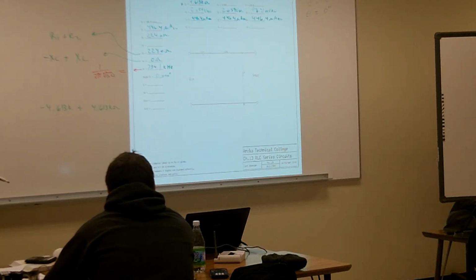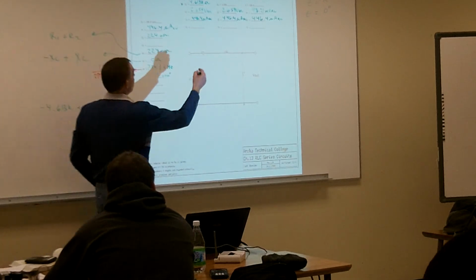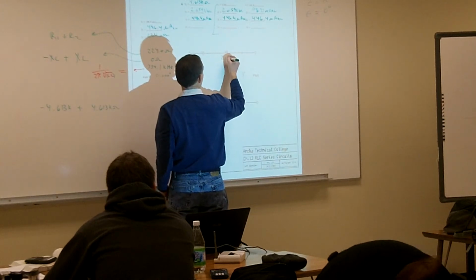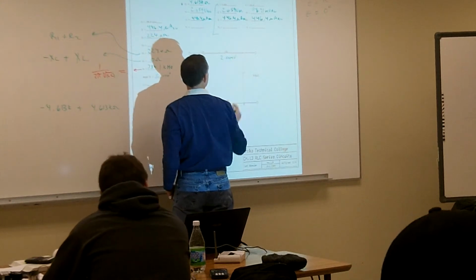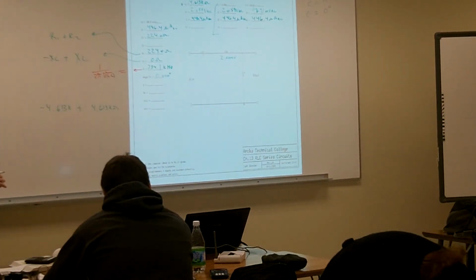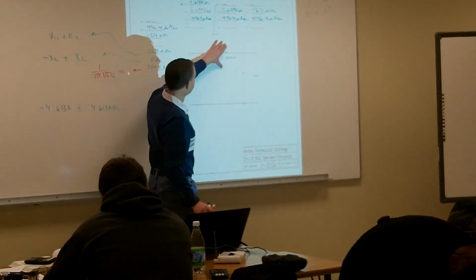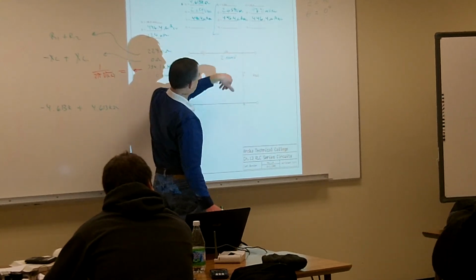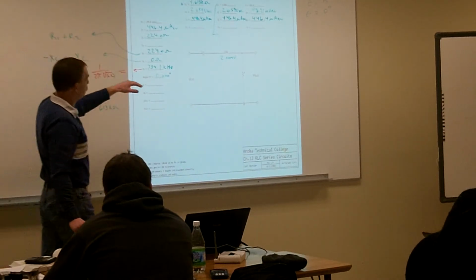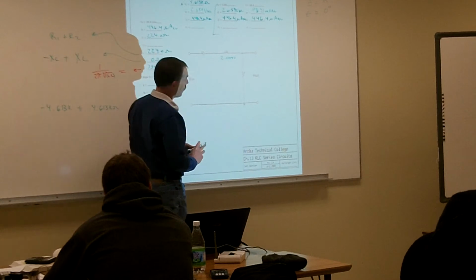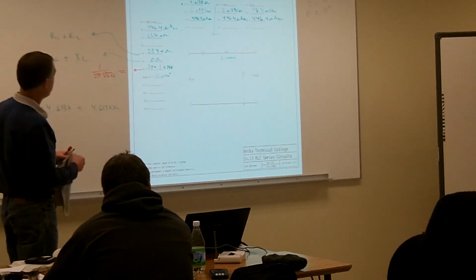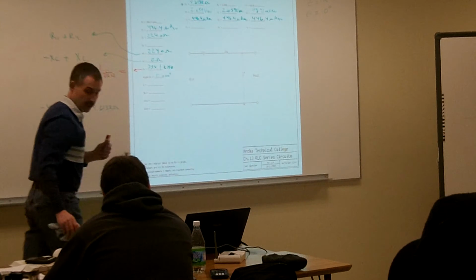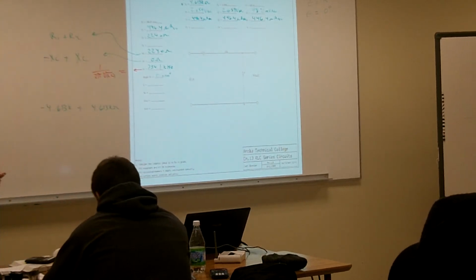It's the wasted power. Yeah, whoever said that. Resistance, yeah. It's the remainder dropped across the resistance of the windings in here. So I got approximately 2 millivolts that are being dropped across that inductor. We can't really measure it, we can't see it, because if we put a voltmeter across there, we're going to see the voltage across the inductor, not the resistance of the inductor. But that extra voltage ends up dropping across the resistance of the winding internally inside the inductor. So that's where those other 2 millivolts go. And that can affect the quality of our circuit. We'll take a look at that when we start looking at more of our graphs.